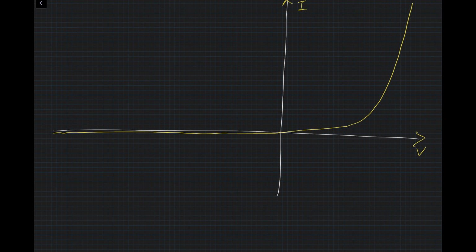So in this case, we are assuming that I can apply negative voltage or reverse bias potential to the diode as much as I can, but in reality that is not possible. So for example, if I'm applying a positive and negative potential over here, which is the high reverse bias, what will happen is you will have very high electric field in the diode, right?